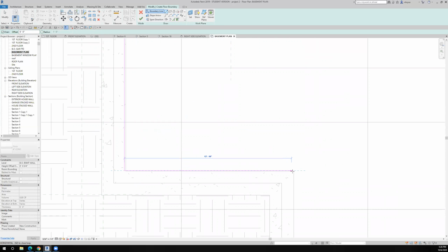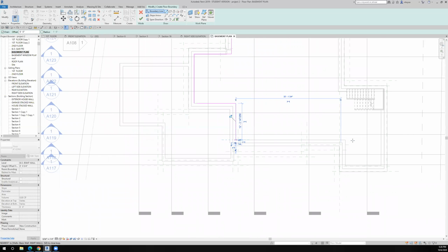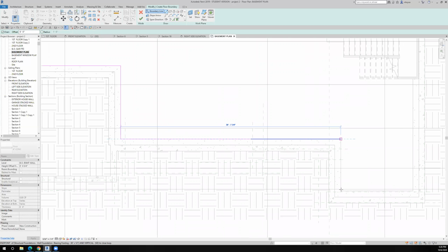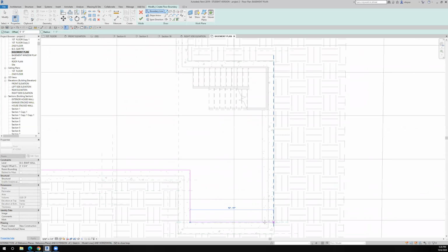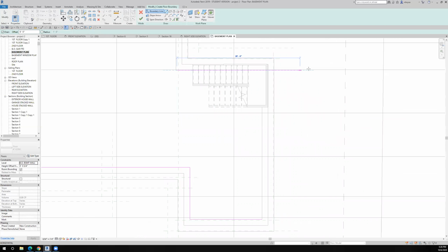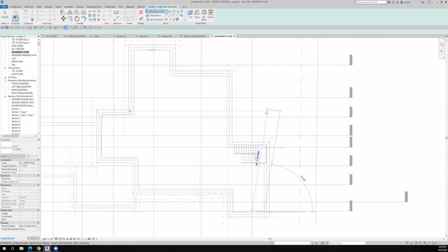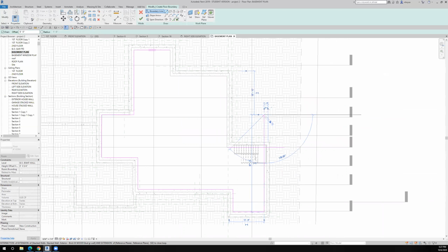I'd like to get back on here. Let's go back to here, okay, so now I'm back selecting the correct lines again. And I'm just following the basement wall, the inside edge of the basement wall is where the floor slab is going to go. I'll make it much wider there. And I don't think I put one in here. It looks like I didn't, so I'll just bring one up here. Let's go straight up. I'll come back and clean that up later.